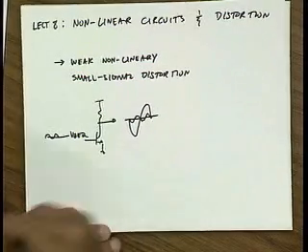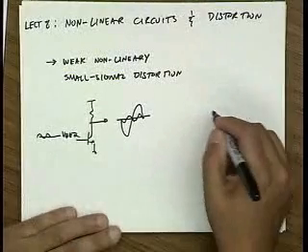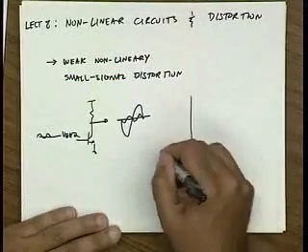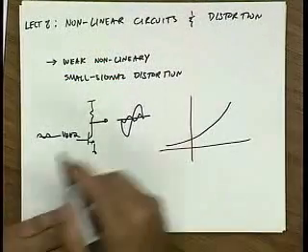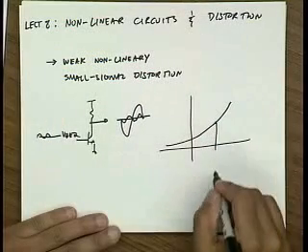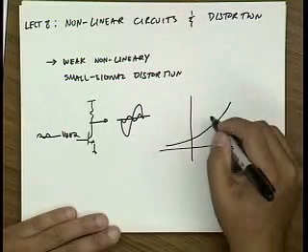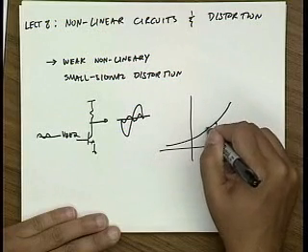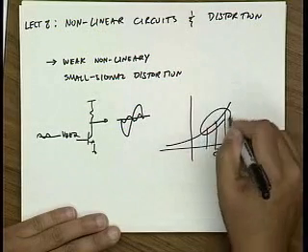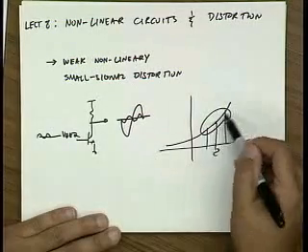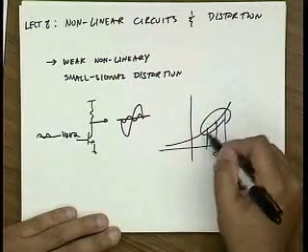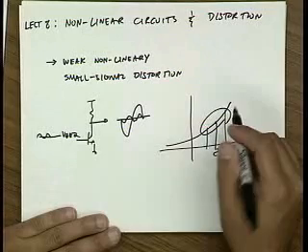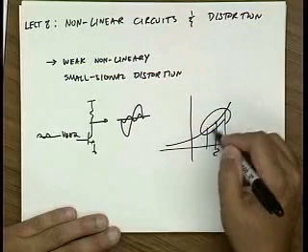Now if we look at, let's say, a typical nonlinear curve for a device, and we consider applying a small signal, then we can see that doing a Taylor series expansion around this point in this region is going to be quite accurate. Even just a simple third order polynomial will describe pretty accurately the shape of this curve.